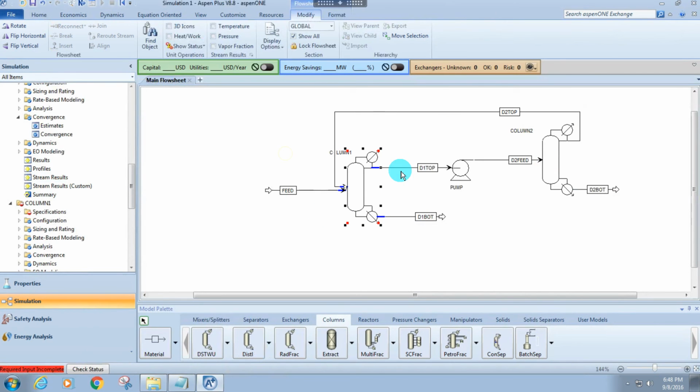So theoretically, you do need some sort of pressure reducer in this recycle stream to go back to 1 atmosphere, okay? Now that we added that recycle stream, let's call this recycle. So our first column will have pure water, and the bottoms product of our second column will have THF, right? This is our product stream that we want with 99% purity and 95% recovery.